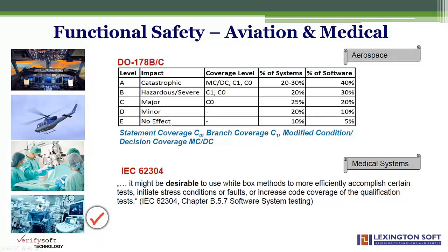Again, here, there is no surprise that level A requires 100% of MCDC coverage. It's mandatory because if you really look at the definition of level A software, it's defined as software which would provide or prevent failure of continued safe flight and landing of an aircraft.